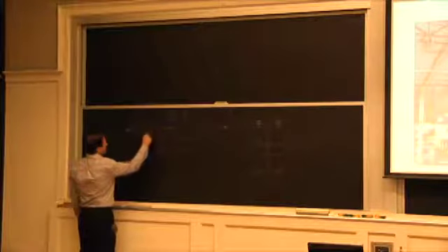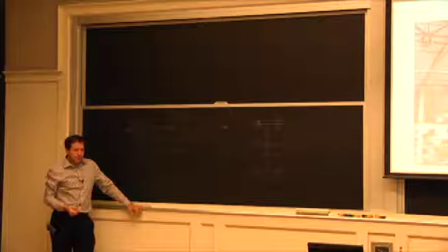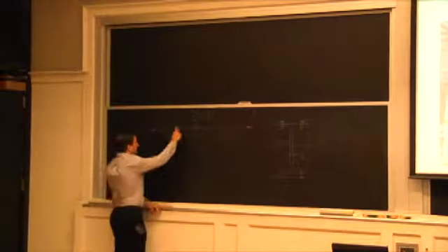And that means, say this is a compression diagonal here. This is tension. This is compression, just by the way it works out. If this is a compression, it's the size of it that I'm designing for. And a lot of the time it would be, say, a round bar that's full, because it's cheaper to buy than an empty tube that is harder to weld at the connection and cut. So a lot of it is based on cost.